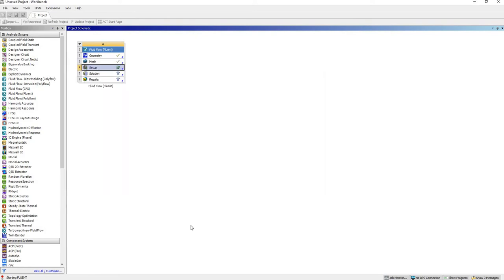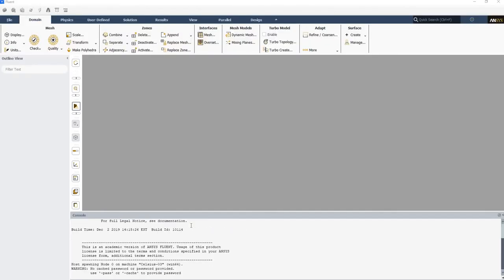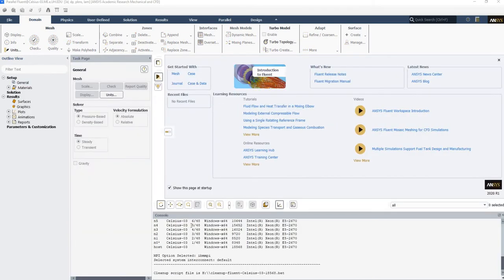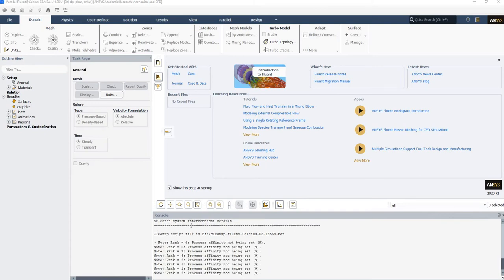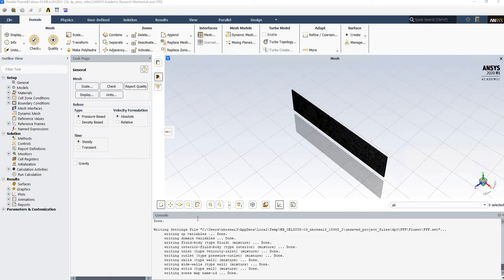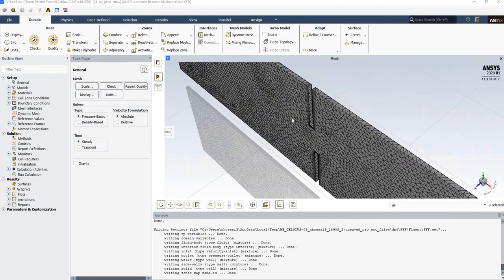Sometimes specifying a large number of processors increases the latency time. So it doesn't matter if you just increase the parallel processors and it will decrease the simulation time. It doesn't happen always. So there is always an optimum number of cores you need, depending on your number of elements and the solver you select. So use an efficient parallel number of processors.